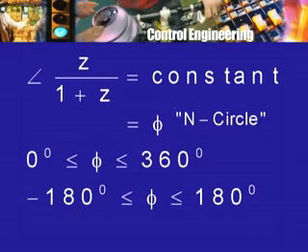So, you had a ready-made set of M circles and a ready-made set of N circles. On those charts, one with say M circles on it, you could plot the polar plot either from experimental data or from theoretical calculations, and then determine the closed loop gain as a function of frequency or get some qualitative idea about that variation. Another chart of N circles would give you the variation of phase shift with frequency.